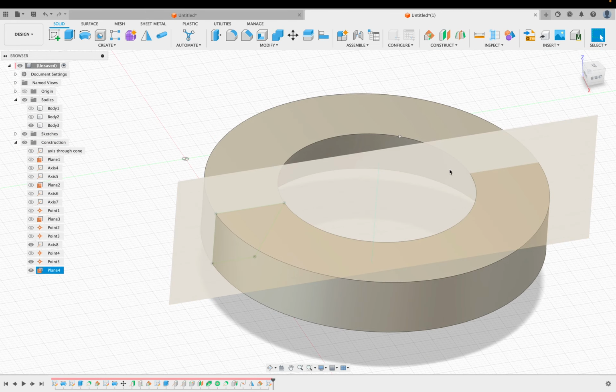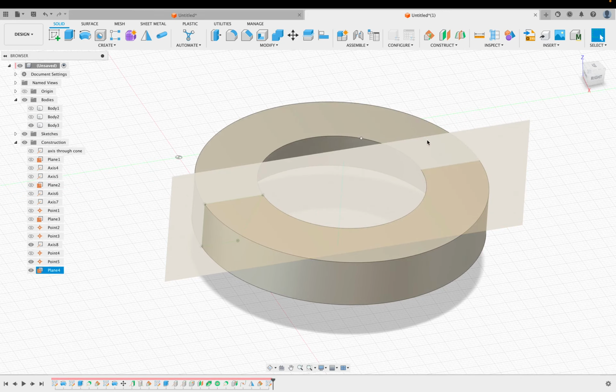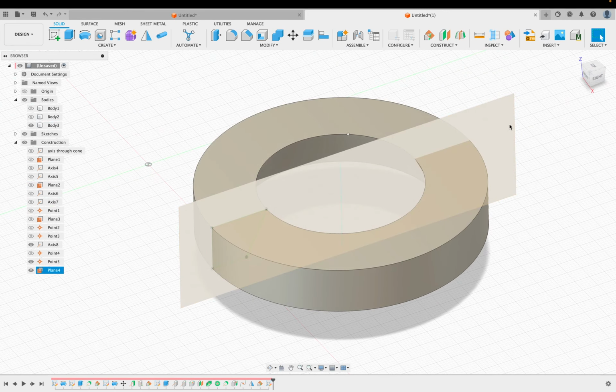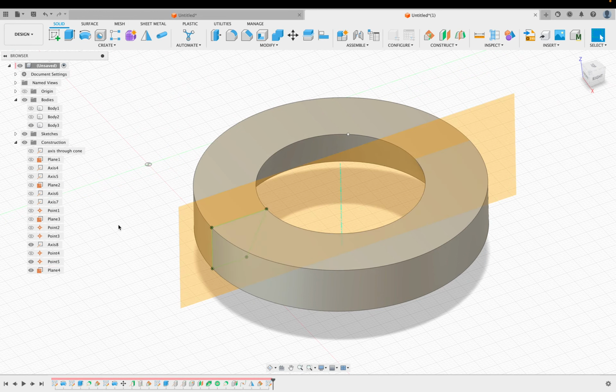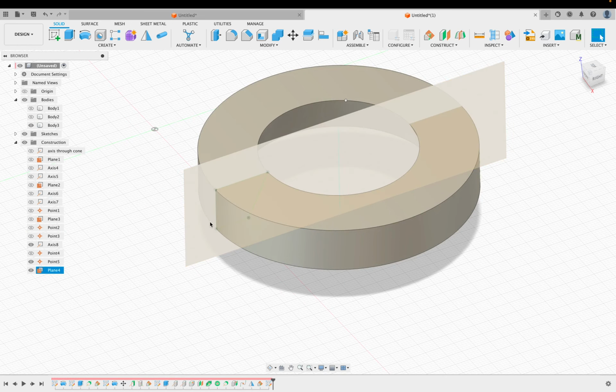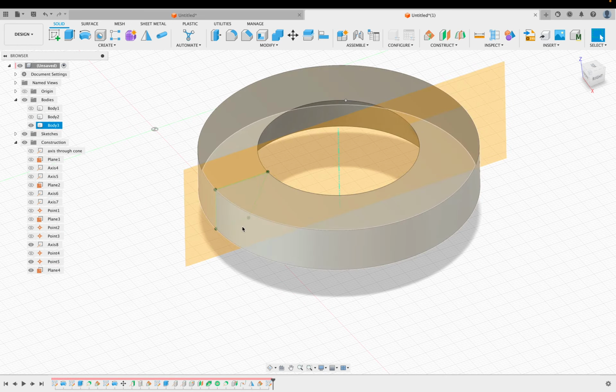Sometimes you will face this. All you have to do is turn the sketch plane around, because even though it doesn't look like it, this sketch plane has a normal. Okay. Which means it has a vector that is pointing towards the positive side and the negative side. And this sketch plane had a positive side and a negative side before we deleted the plane.